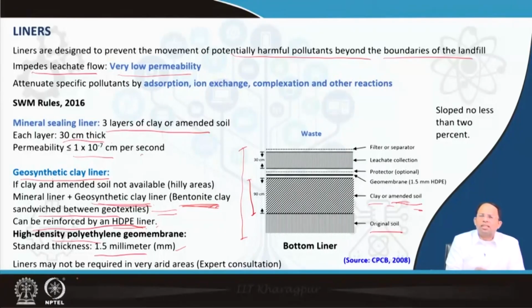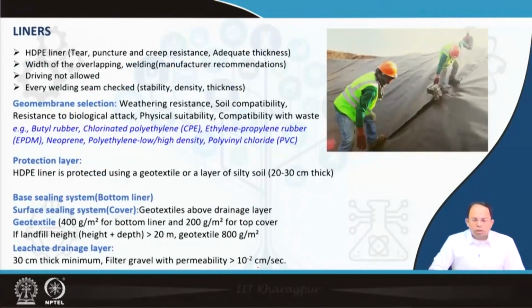Liners are required in most sanitary landfills, except in areas which are very, very dry, and with expert consultation we can avoid putting certain liners. So as you can see over here, this is that HDPE liner which is being laid. These kinds of liners are laid at the bottom, and at the top as well.